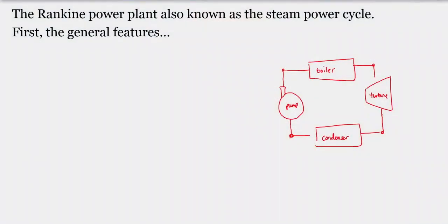And what they are is essentially a lot like your oven. So you have a really big box, very well insulated, and we have a serpentine of steam tubes or pipes that run through the boiler in order to heat the steam that is the working fluid. So again, this is steam, and that's another way of saying our working fluid is water. Okay. And again, this heat transfer source can be a number of different sources.